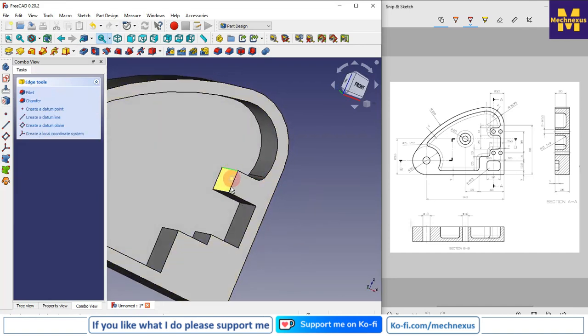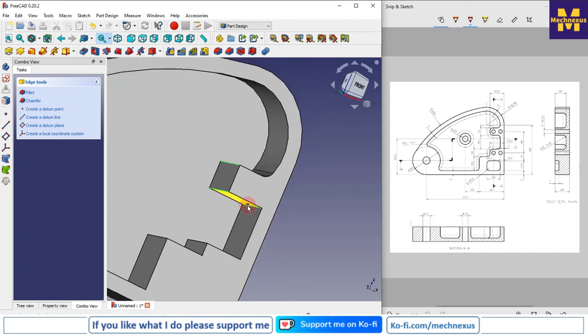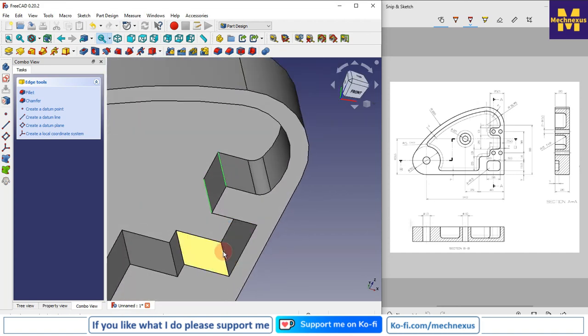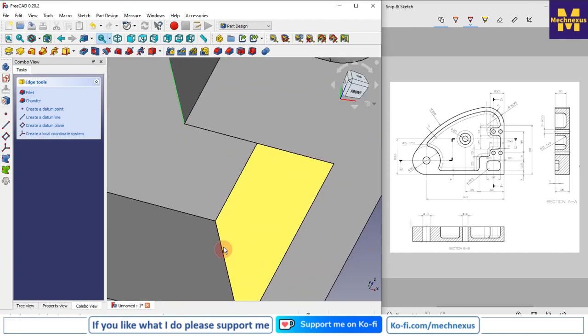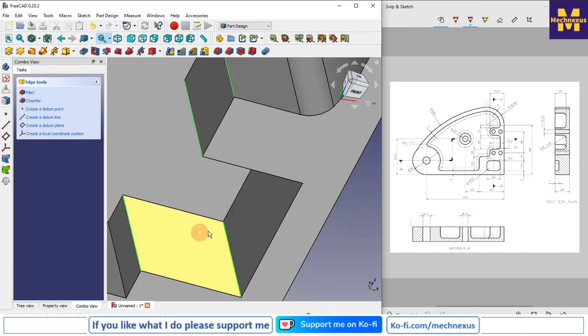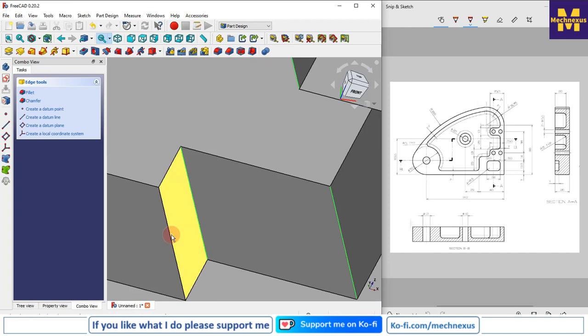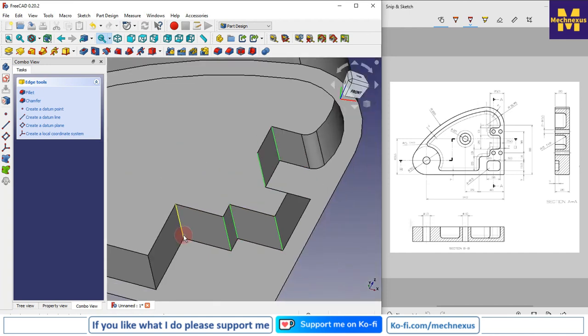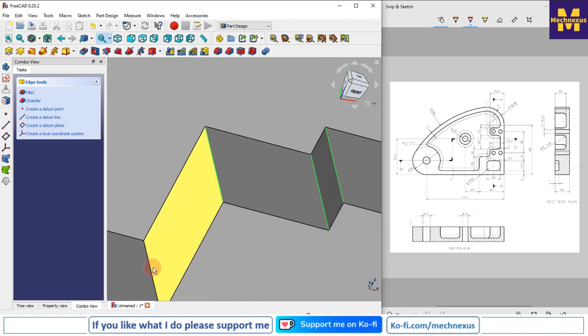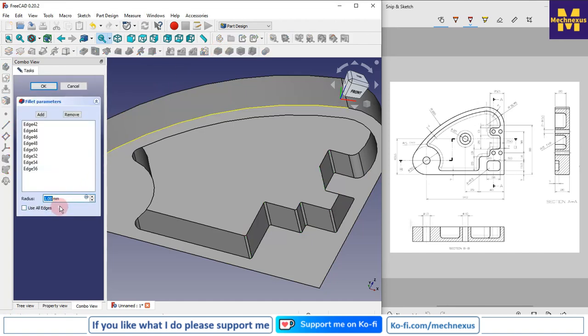Now I will select all the edges. We'll select the fillet and give the 5 mm.